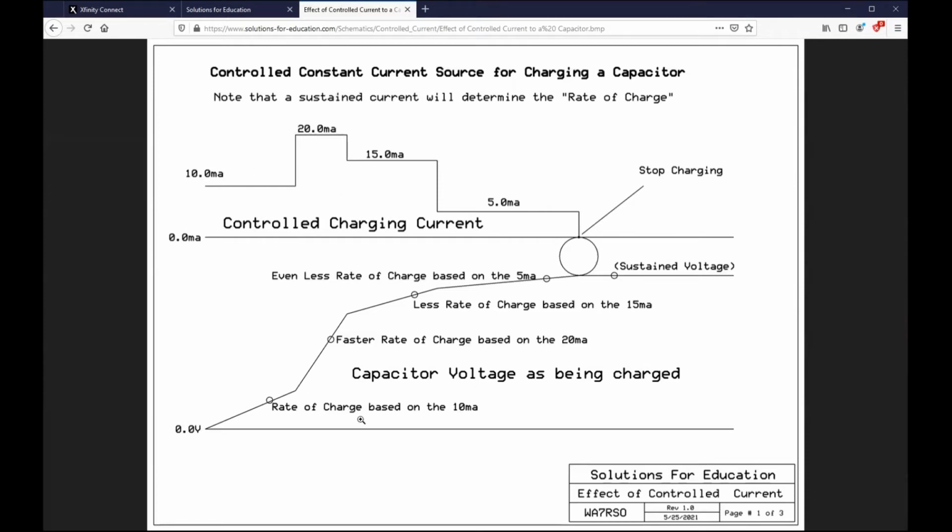Well, the voltage is here. Now, I will grant you this. It may be possible that to maintain 10 milliamps here, as the voltage here rises, these two voltages will be in contrast to each other. Therefore, this circuit over here is making adjustments, but that's what makes it a current source. It will make whatever adjustments it needs to in order to maintain 10 milliamps constant.